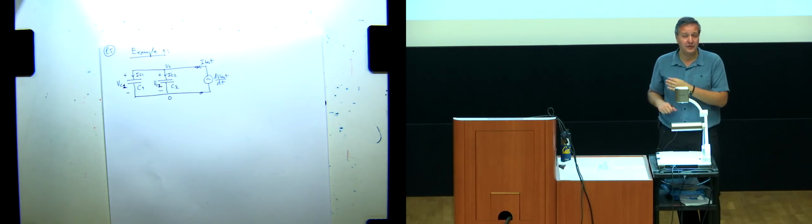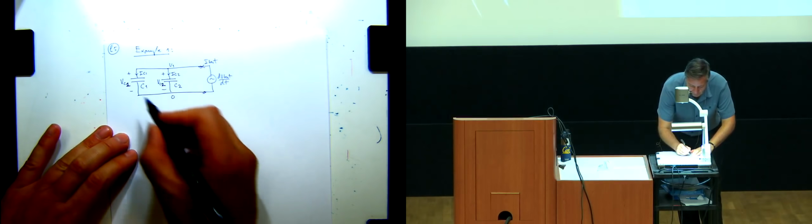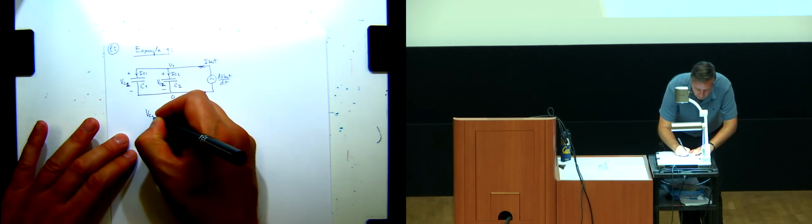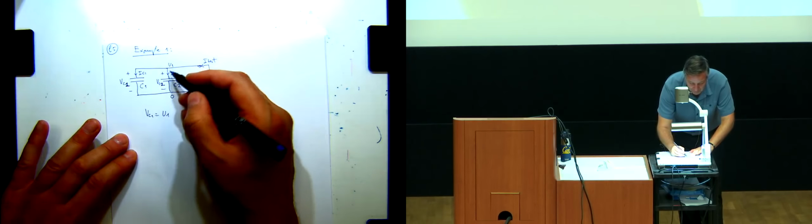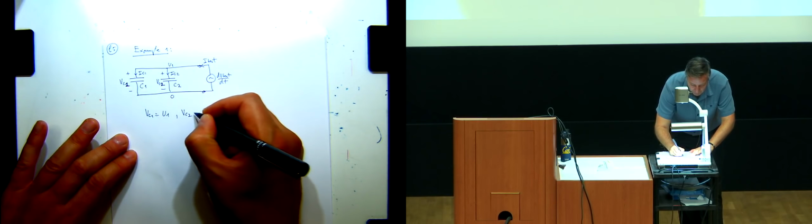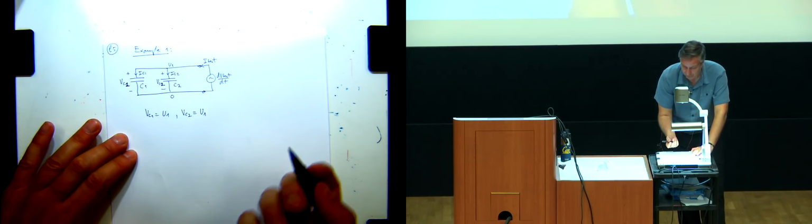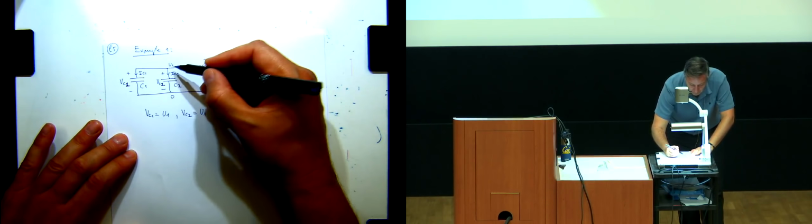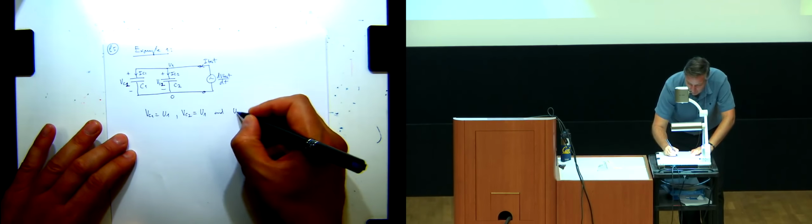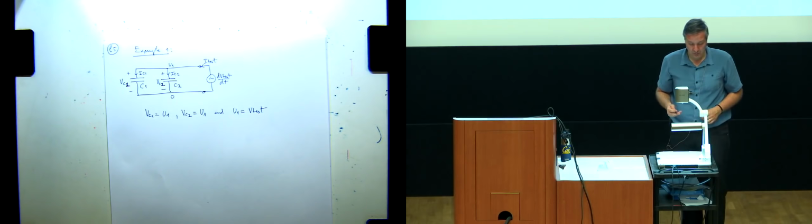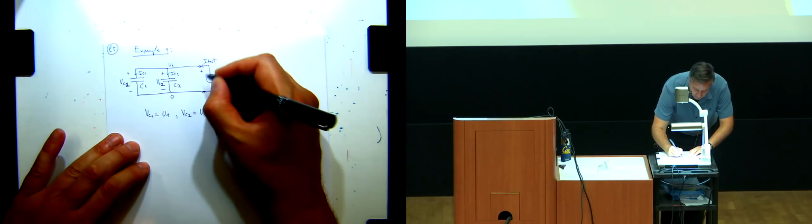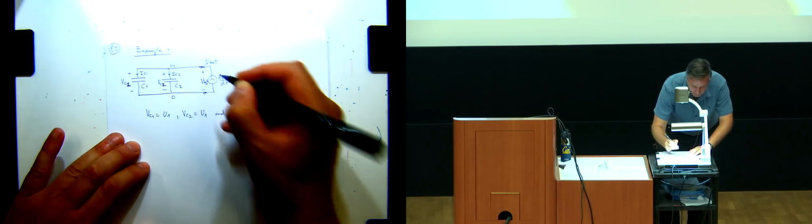So let's just write out what things are here. VC1 equals U1 minus 0, so that's just the voltage definition across. Same for VC2, and that's what you were saying, right? And we also know that U1 minus 0 equals V test. Okay? We're applying a source here, so this is V test, right?